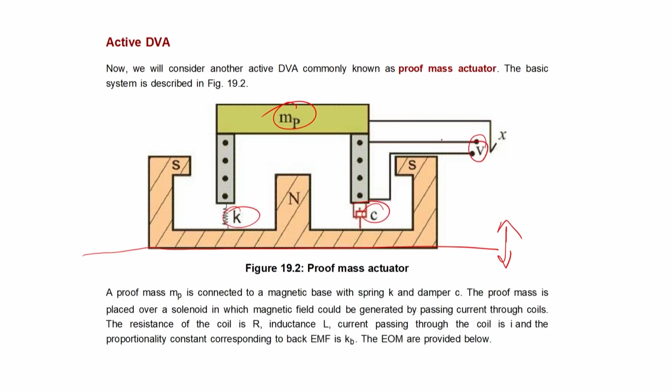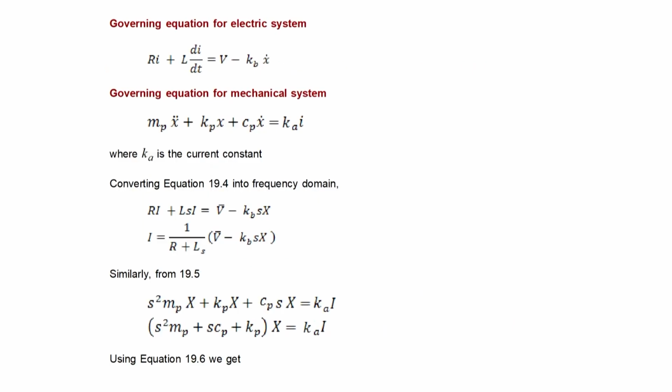By applying the voltage and controlling the polarity, you can create either a north or south pole in a manner that it can either get attracted towards this system or repelled from it. So, you can actually generate a vibration in this system. If this force vibration and the original vibration are in opposite phase, they can basically control each other.